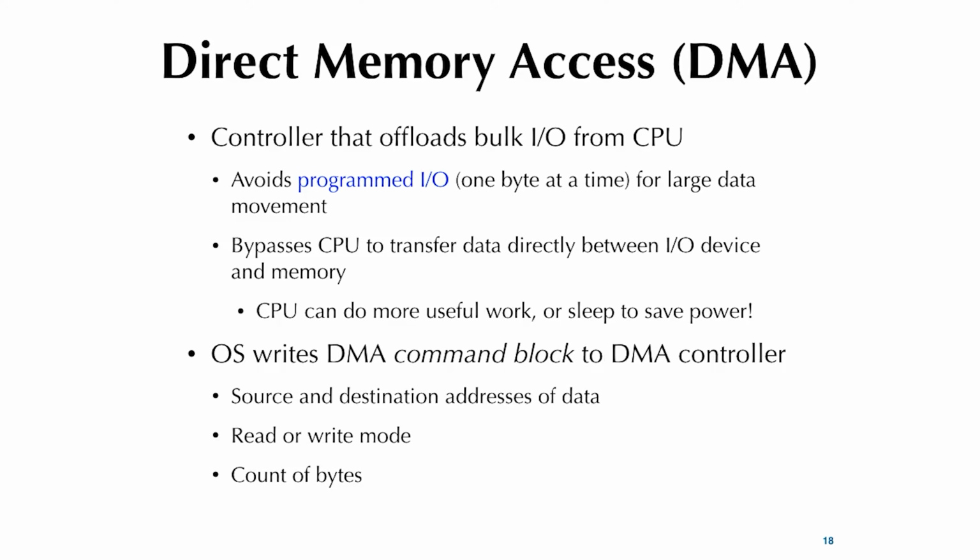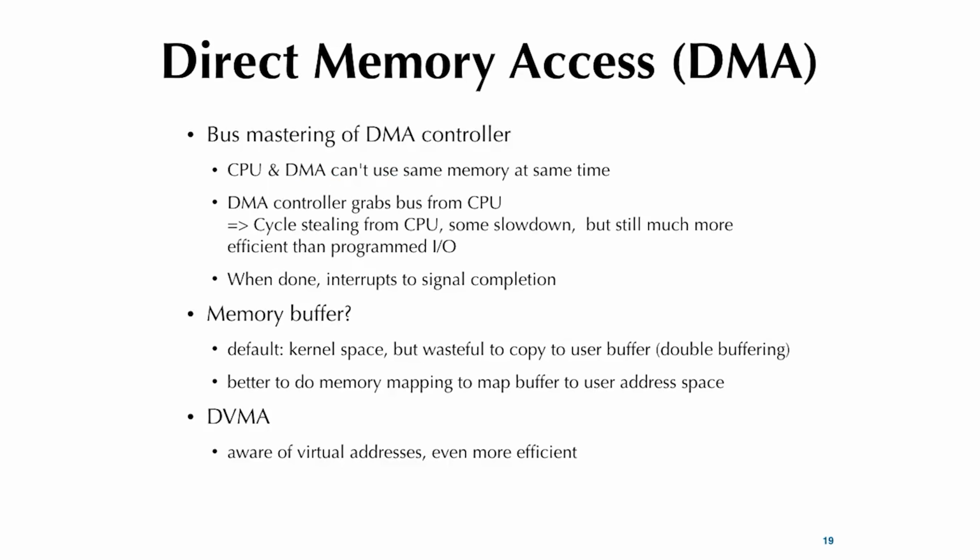And then it sneaks in and does the transfer between devices. It has its own buffer as well, so that way it can use the memory efficiently and doesn't get in the way of the processor. And if the processor gets a cache miss, okay, it goes to memory. And then DMA, of course, has to yield, back off, and let the processor have priority.